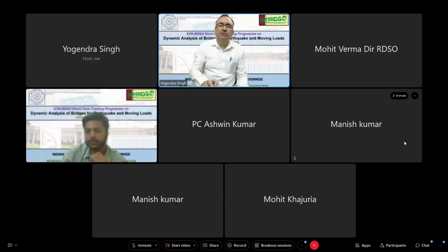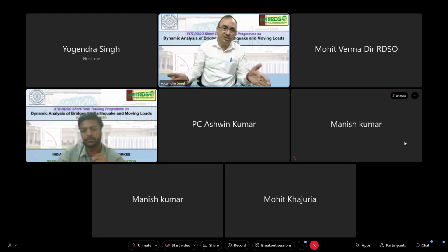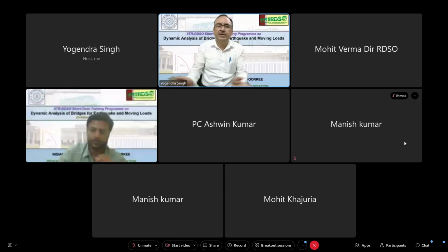So CQC will be used to combine the effect of different modes in a direction. When I perform the X direction analysis, I will consider several modes in X direction also. We will use CQC there. Similarly, I will perform the analysis in Y direction, and I will use CQC. And then these two can be added by SRSS. And we can see that SRSS is nothing but the square root of the sum of squares of X and Y.